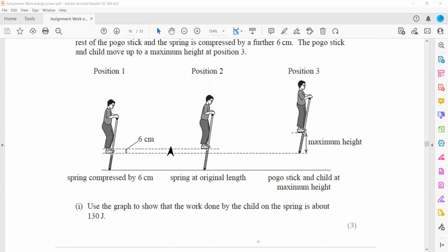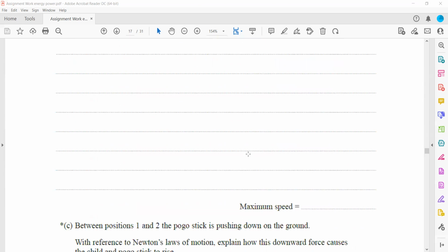So we'll calculate the potential, because the energy stored here is the elastic strain energy. But when he moves, it will have potential, and he's having a maximum speed, so he will have kinetic. So both energies: the potential is mgh and kinetic is half mv square. So the total elastic strain energy is the sum of potential plus kinetic. So we'll calculate the speed in this manner.